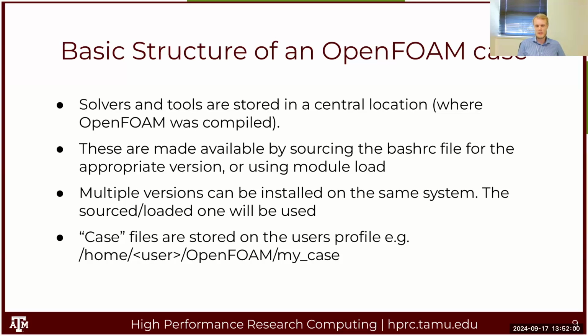If you're using your own system, you're probably using the bashrc file in your home directory. If you are on ACES or any other cluster, you're probably using module load. Just so you are aware, you don't need to stick to one version of OpenFOAM. You can keep as many as you like because they may all serve slightly different purposes for you. And case files are stored in your user profile, either in home, or if you're on HPC, it should be Scratch.